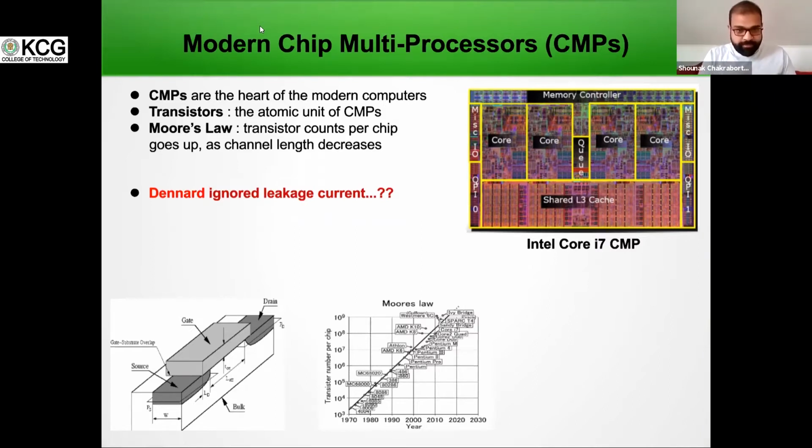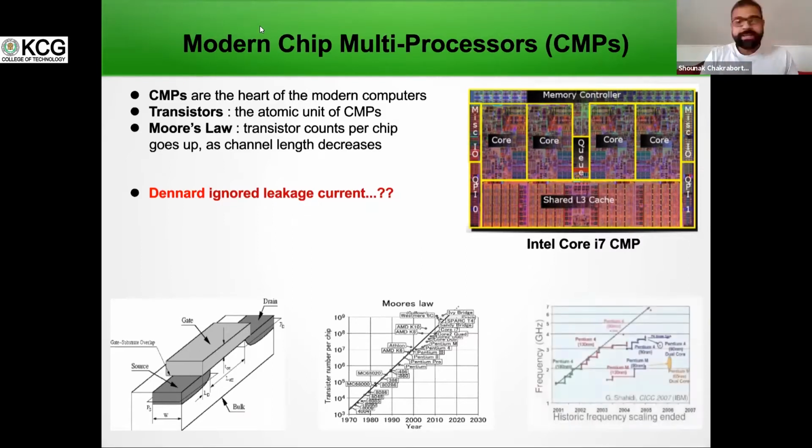But there was a problem. You have accumulated more transistors on a single chip, which may drastically increase the power density on chip. Another scientist called Dennard gave another theorem, called Dennard scaling, where he talked about how the decrement in channel length reduces the delay of the transistor.